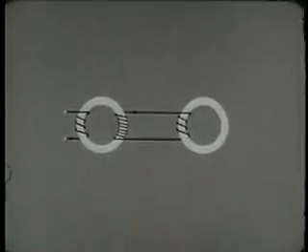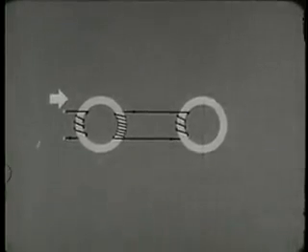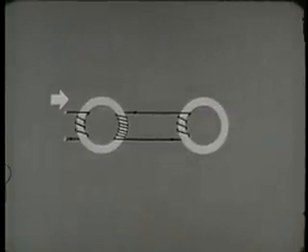By connecting in a second core on the right, we can see more clearly what the problem is. Now, the first core's output winding is directly connected to the input of the second core. This input has been wound so its polarity is the same as that of the input of the first core. The dot side is below. In a typical core circuit, current flows in only one direction, into the input of the first core. We'll take the non-dot side for our example.